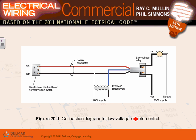To understand the low voltage system, guys, give me your undivided attention. Here's what happens. I have 24 volt here. There is a low voltage line coming in here. It's not shown. There you go. If you look at my 24 volt, when I turn this to red, it's on. When you connect this one, guys, you will energize this circuit, a little coil that's coming right in here, and this will close these contacts. And now I have 120 volt across the light. The light is on. Can you guys see that?